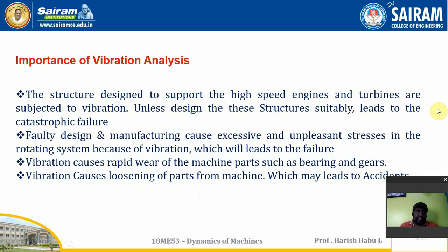So what is the importance of vibration analysis? If a structure designed to support high-speed engines or turbines is subject to vibration, failing to design the structure suitably leads to catastrophic failures. Faulty design and manufacturing cause excessive and unpleasant stresses in the rotating system because of the vibration, which leads to failure. Next, vibration causes the rapid wear of machine parts such as bearings and gears.